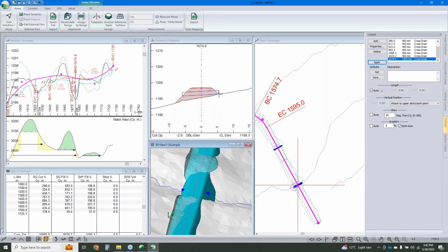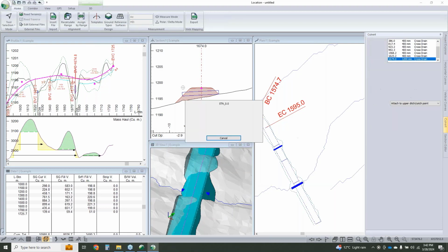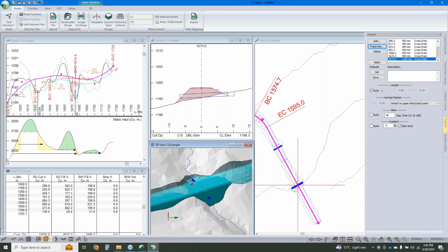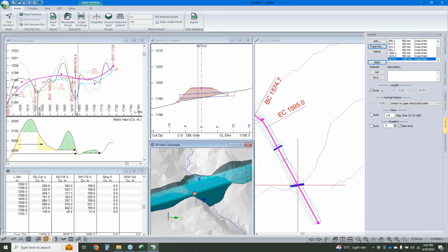So here I've got vertical offset 1.8. So my default ditch isn't going to require a pipe there, but I'll say let's add in a ditch width of 2 meters, depth of 2.3, 2 meters wide. I'll hit OK. And here we can see we've kind of forced that into adding in a sump. We can control the position, or I guess the skew, I should say. It's all position related. So change the skew number.